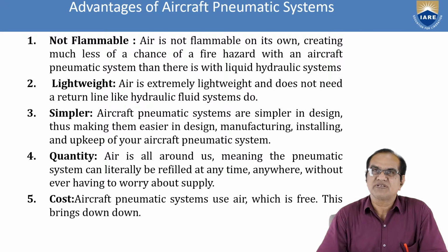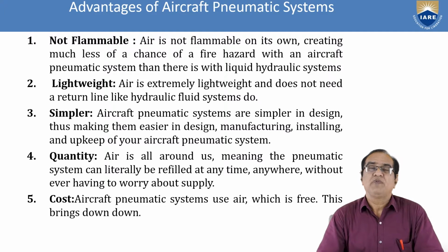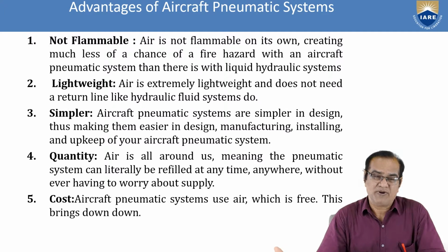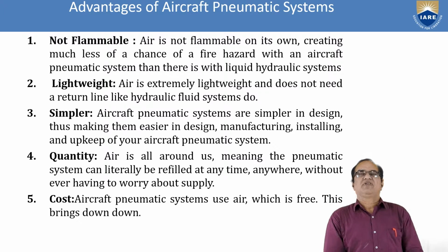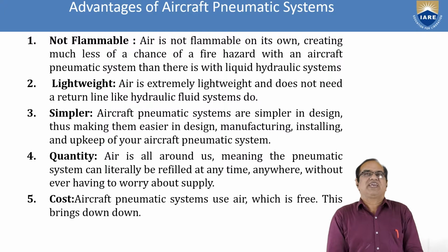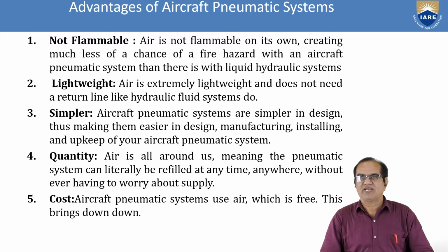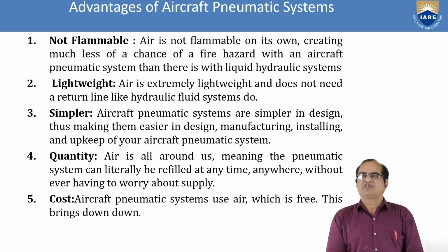Advantages of aircraft pneumatic systems. We have seen that hydraulic systems use petroleum products, and if you use them at high temperature, there are chances of fire taking place. But a very good advantage in the pneumatic system is that it is air. Air is not flammable on its own, creating much less chance of fire hazard with an aircraft pneumatic system than there is with a liquid hydraulic system. So there is very little chance of fire in the pneumatic system compared with the hydraulic system.